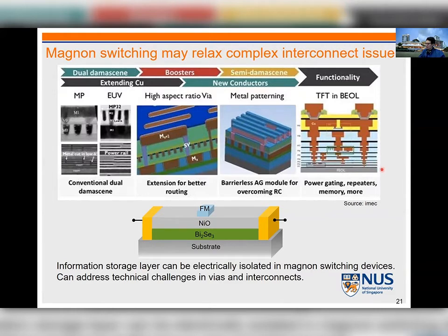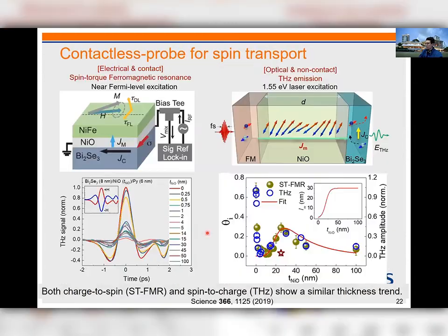And basically that is achieved by having holes called the via, and we have to have a physical contact between the current injection layer and the magnetic elements. But if we can do this, we can put an insulator material in between the current flowing layer and the magnetic or memory object. So we can basically isolate those two components.